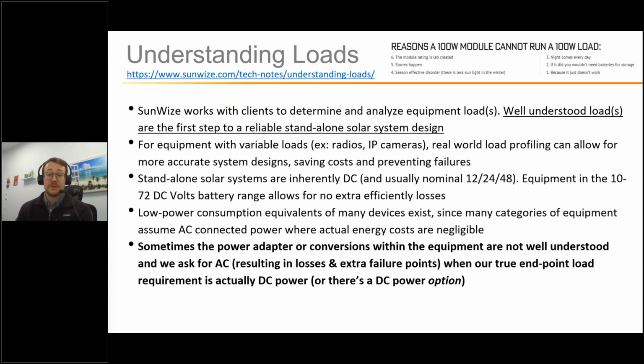And sometimes those loads are not clear. Sometimes we're only presented with a data sheet that may list a minimum power or a maximum power, and that could be a broad range. At the end of the day, there's no substitution for good field-driven data. That is easily something that can be accomplished with the onboard data logging or remote monitoring capabilities provided by Morningstar charge controllers. So running a pilot project to understand real-world loads, if you don't actually know, can be helpful or very helpful depending on the specific project and the volume and so on and so forth.